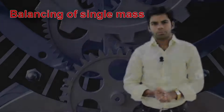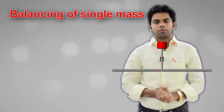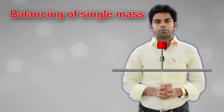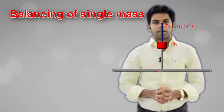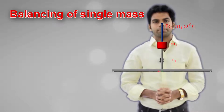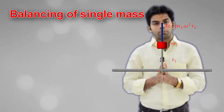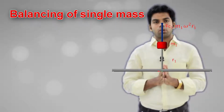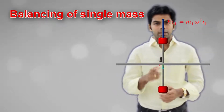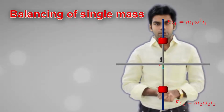I will tell you how. Suppose we have this unbalanced mass m1, which is at a distance of r1 from the axis of rotation, and because of this a force is produced, suppose Fc1, whose magnitude as we know will be m1 omega square r1. In order to balance this component, we have to put an equal and opposite force. So we will put a mass m2 at a distance r2, and the force produced by this m2 is Fc2.